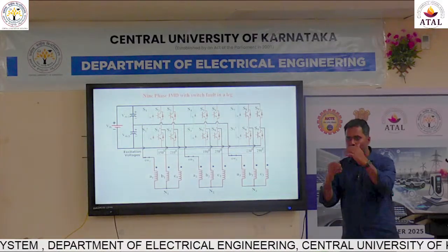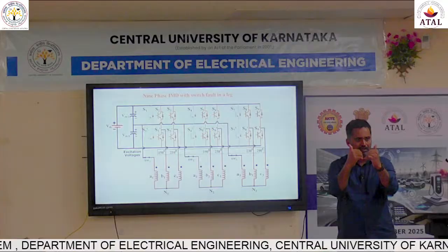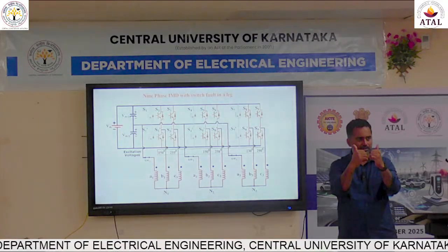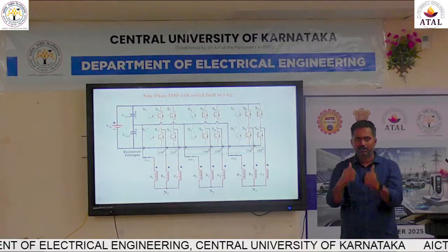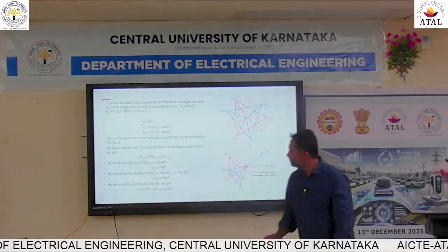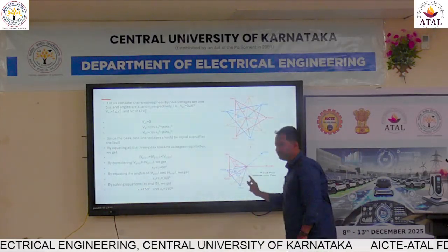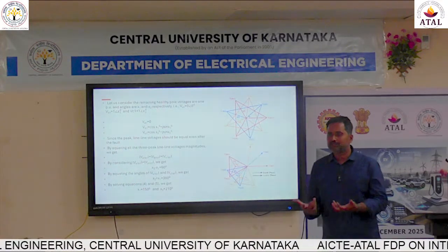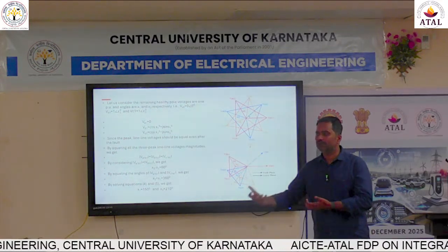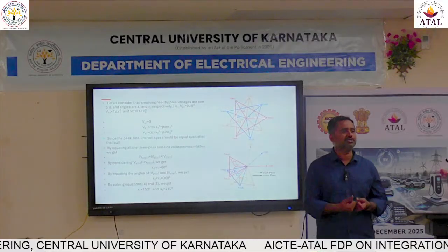Now from one winding to the other winding you have slots, and between all of them there is an insulation. If the voltages are the same, the insulation requirement will be less. Whereas in the next case, what has happened? This has been shifted. When the neutral voltages are shifted, where will the voltage stress go? There should be insulation, it has to be ready.